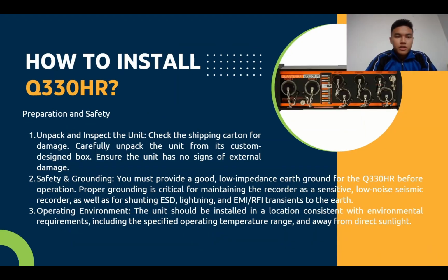The next part is how to install the Quanterra Q330HR. The first one is preparation and safety. First, unpack and inspect the unit. Check the shipping carton for damage. Carefully unpack the unit from its custom-designed box. Ensure the unit has no signs of external damage.